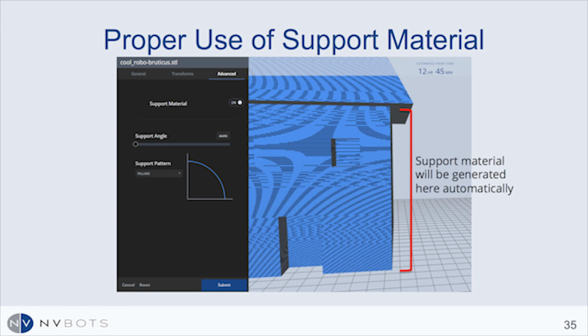It's hard to think of a very particular use case, but there may be cases where more advanced users would want to go down that route and say, I want material only below 87 degree angles for overhangs. But typically I'll leave that to be automatic, and when you have features like that need support material, it'll automatically generate it there. And it may or may not generate support material over that door and within the windows.